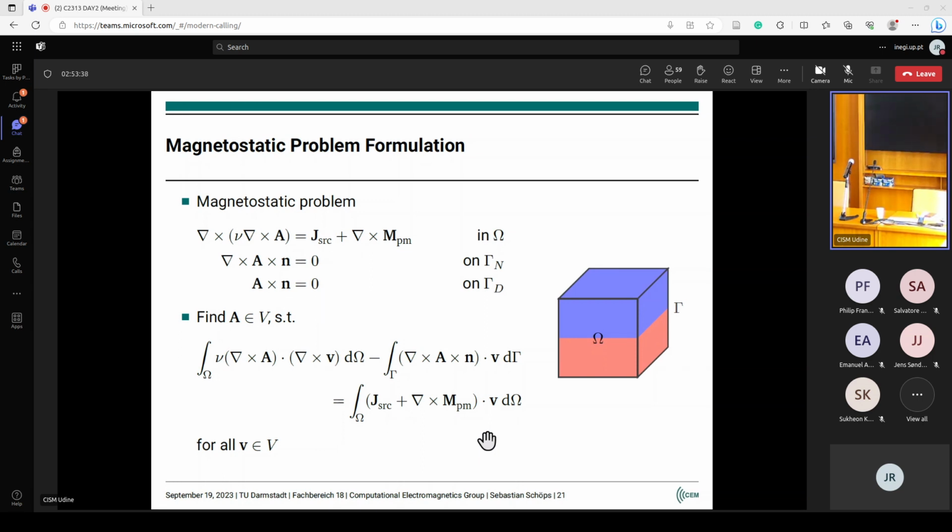Now for electric machines to move, and that's one of the connections I want to make to the talks we heard this morning, they pop up also here. If you do a moving formulation, because in the machine the rotor will turn in the stator, you cannot solve the problem on one fixed domain, but you have to deal with, let's say, two domains. So here again, weak form.